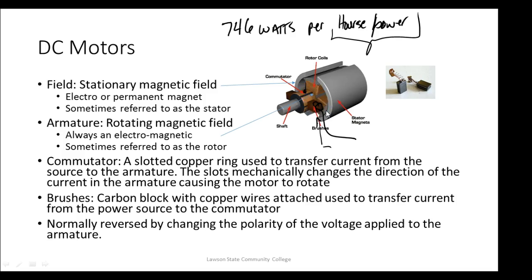We got one over there in the motor controls lab. If y'all take motor controls, whoever teaches that should show you that motor. What they did is they took the covers off the brushes, and then they just left them off. And that motor is just torn to pieces because now it got gunk in there and got it on the commutator. It causes the brushes to get soft.